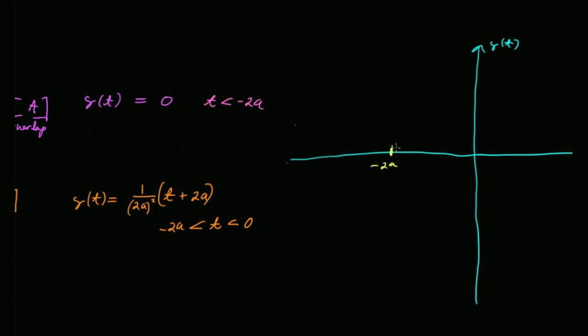What is the value of this equation at t equals 0? Right. So this will be 1 over 2a. Tremendous. Just out of curiosity, what does this equation predict for t equals negative 2a? 0. This is important. The way convolution works, as long as there are no impulses, which screw everything up, it's interesting that you don't get discontinuities in your convolution integral.